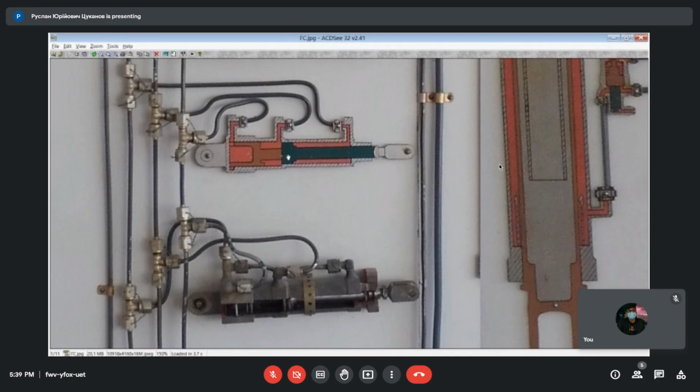As a result, all the pistons are retracted, and the retracted state of these pistons corresponds to extension of the flaps, a 50 degrees extension, maximum deviation angle. It's a landing position. When you need to extend the flaps to the takeoff position, 25 degrees, half of this motion, you supply pressure to both extreme lines, here and here.